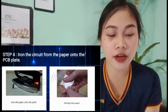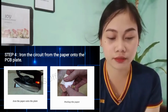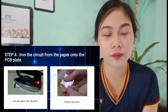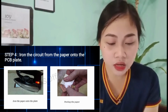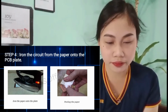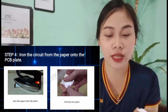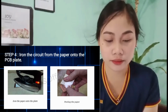The heat from the iron transfers the ink printed on the glossy paper to the copper plate. Caution: do not directly touch the copper plate. It will be very hot from the iron. After ironing, place the printed plate in lukewarm water for about 10 minutes. The paper will dissolve, and then you can remove the paper gently. Remove the paper by peeling it from a low angle.